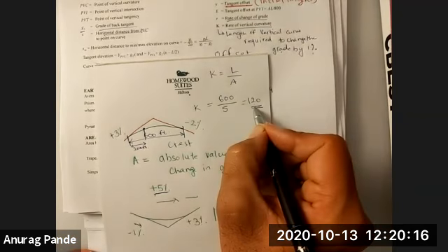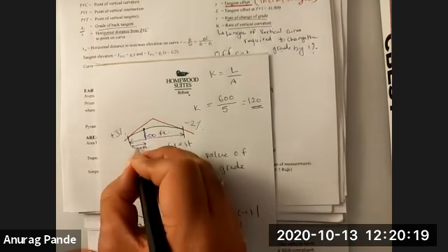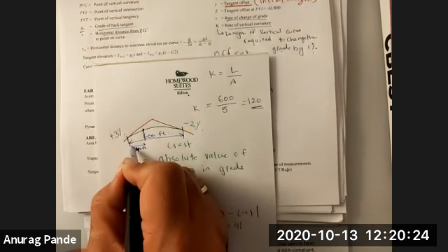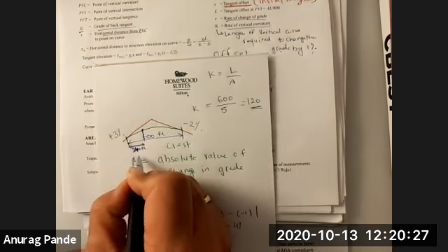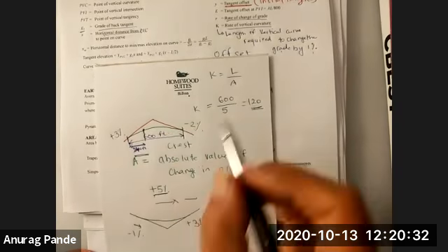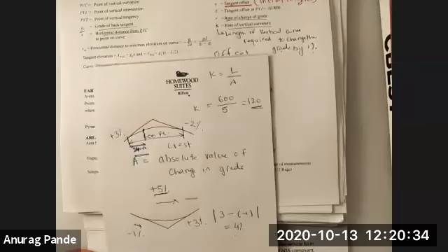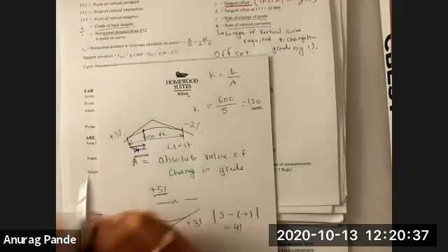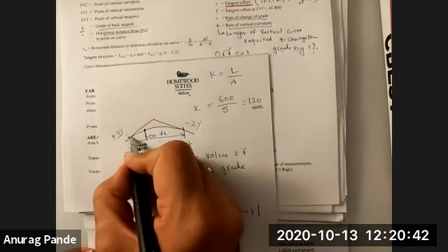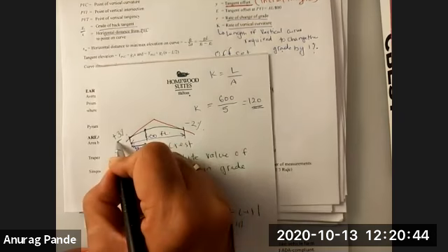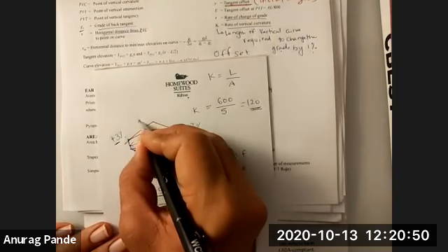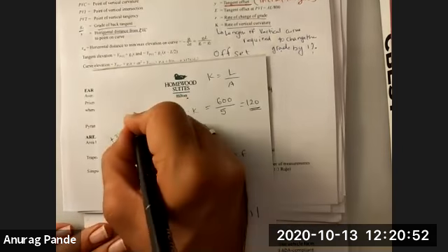Let's say you go not 200 feet, I'm going to make the calculation easier, but 240 feet along this curve. What will be the slope of the tangent here? If you go 120 feet, you change the grade by 1%. If you go 240 feet, you will change the grade by 2 percentage points. So by the time you hit this point on the curve, you would have gone from plus 3% and changed it by 2%, and the grade at the tangent here would be 1%.